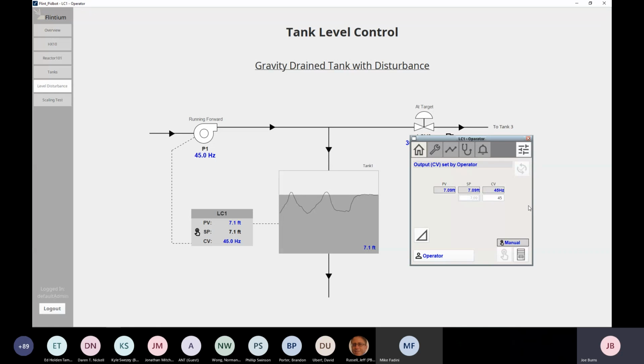If we're controlling a temperature loop, and I started heating way back here in the pipe, well, that's really not going to be reflected downstream for a while. So transport delay is a classic example of dead time in your process, whereas a deadband is usually around a zero crossing in your PID controller.